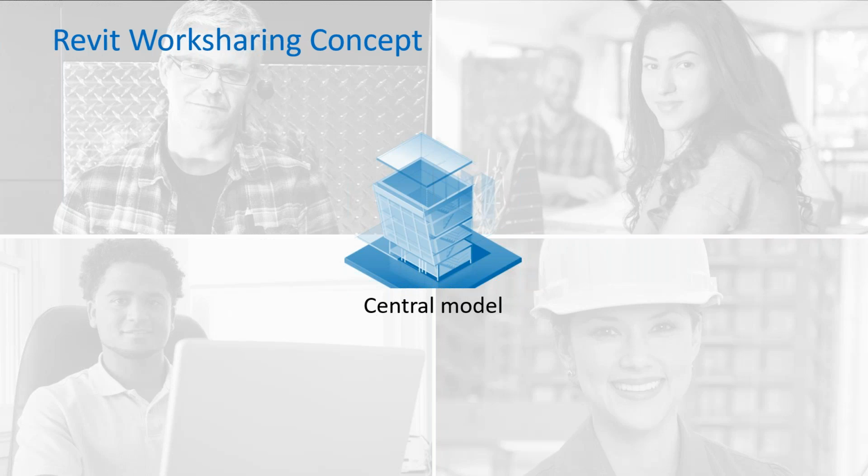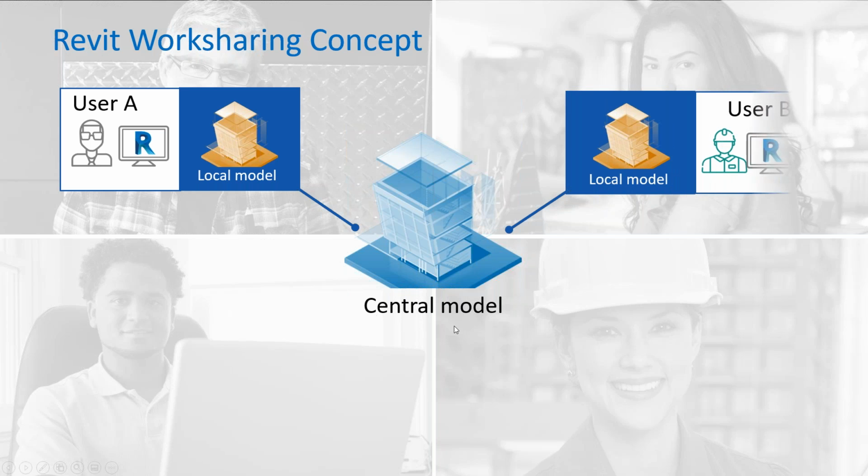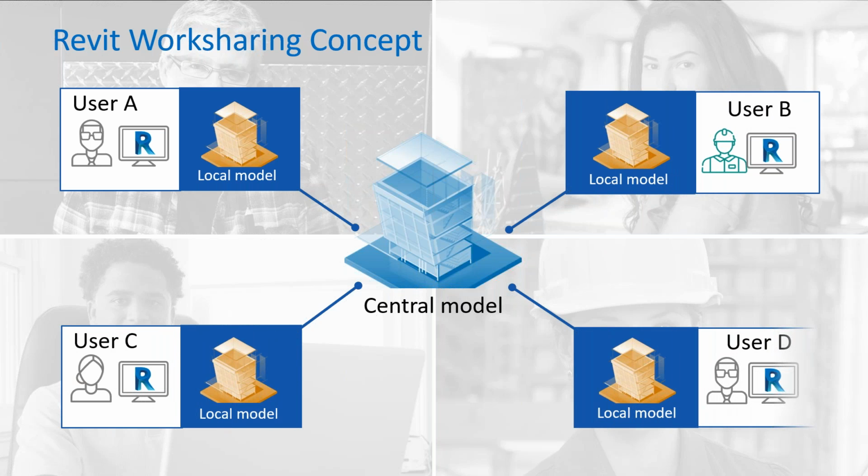It's obviously a design tool, an AEC (architecture, engineering, construction) design tool, but it's also one of the tools that allows us to design collaboratively. And it means we set up Revit in something sort of a client-server mode. So it essentially means that we're going to have a central model somewhere, and that somewhere is quite important later on when it comes to BIM 360 Design. But we have in general a central model, and then we're going to have different users all working on that central model. They're actually having a local copy.